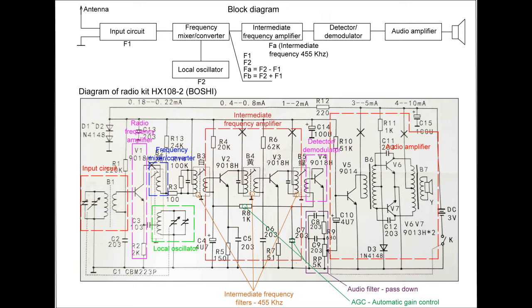The superheterodyne receiver, receiver with frequency change. In the case of these receivers, the signal received by the antenna undergoes a frequency shift/conversion, because the received signal is mixed, in a mixer, with a signal generated by a local oscillator. At the output of the mixer, four frequencies result: the frequency of the input signal, the frequency of the signal generated by the local oscillator, the sum of the previously mentioned frequencies, the difference of the previously mentioned frequencies.